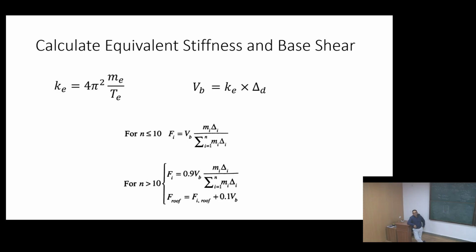Tomorrow, Professor Datta will teach you more about plastic hinges and pushover analysis, which is kind of a requirement for direct or any performance-based design. You can do pushover analysis by hand, but that's a lot convoluted. We generally use some kind of software, but he'll teach you the concepts of pushover analysis, and that's one of the techniques to do performance assessment or performance check for your performance-based design.